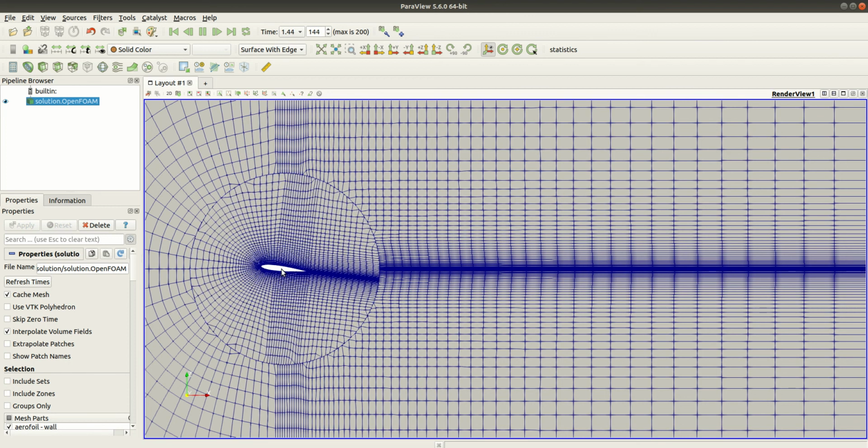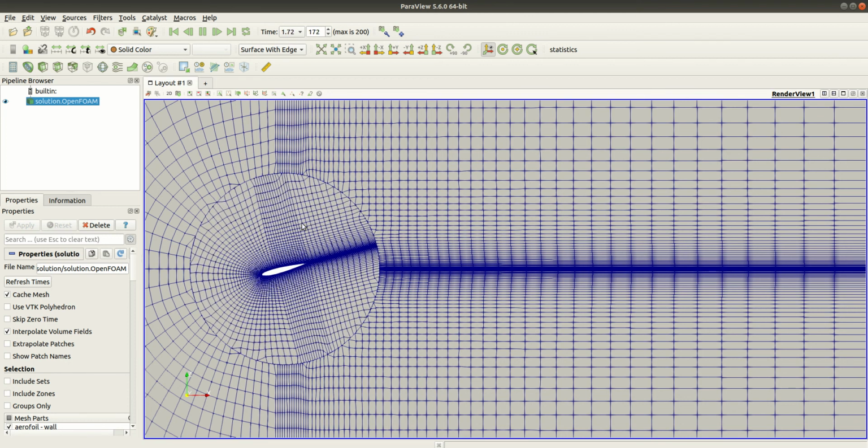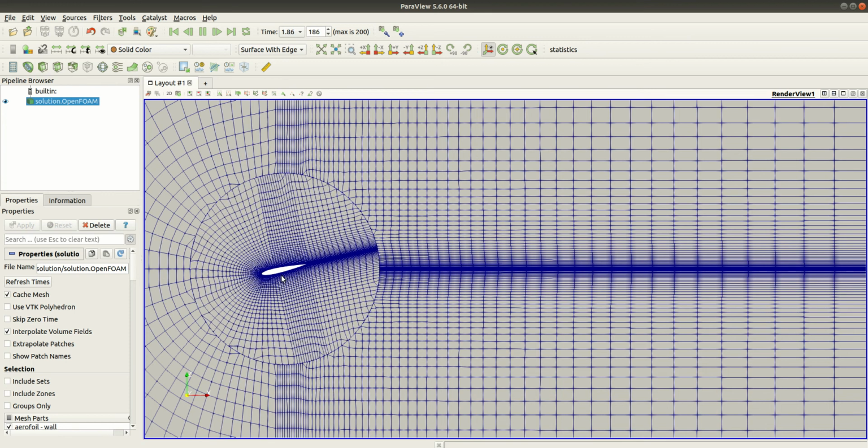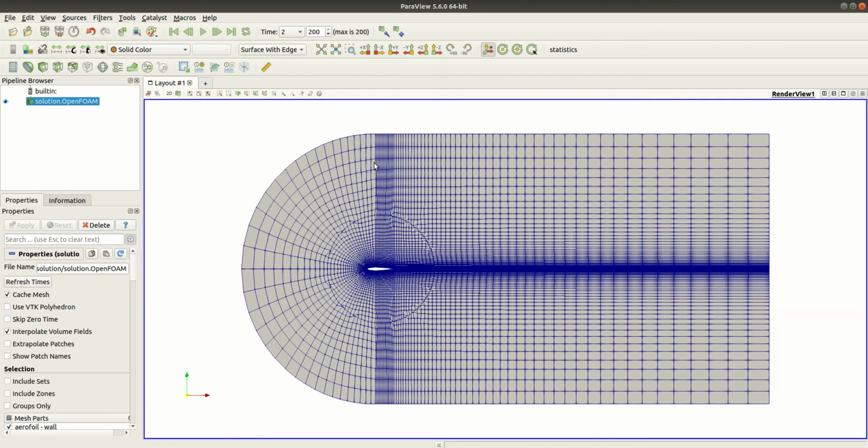So now I think we closed the circle. In the first tutorial we talked about the block mesh and advanced use of block mesh in order to define a structured mesh, which is a little bit deformed here because we used the snappyHexMesh utility, but is still recognizable.